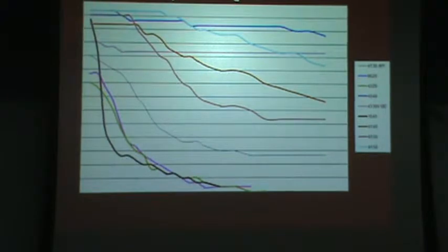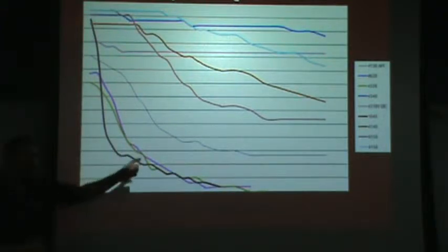I don't know if I have another graph, so I'm going to introduce this now. If it shows up in the graph later, that's fine. So a lot of specifications, both industry specifications and customer specifications, will define the Jominy results that they want for the material to be used for certain parts. Now, the ASTM specification that does that is specification A304. And it has a whole bunch of very common grades and then what the Jominy curves should be. So they've got charts that look like this for each grade.